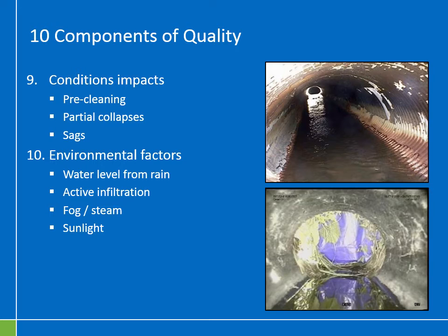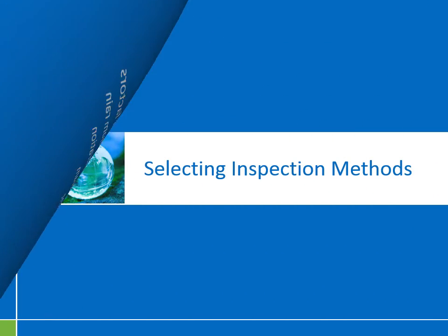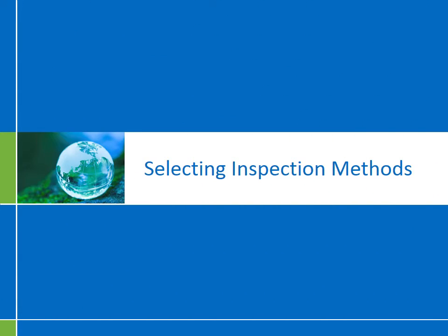So what contractors do to deal with this, a lot of times, if that's an issue, is take heavy tarps and lay them over the other end of the culvert, and use the onboard lighting to light the inside of the culvert, and they're going to keep that sunlight from getting out there and into the culvert. So those are a couple of quality control considerations when you're doing a video inspection.